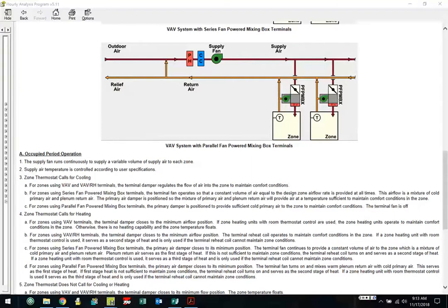And we do that with this preheat coil. So what goes on in the wintertime is sometimes we'll see this coil be indexed. The reason that coil would be indexed or opened up, the valve starts moving on that, is if the entering air is real cold, and really what it controls to is the leaving air. We want to maintain a minimum temperature here.